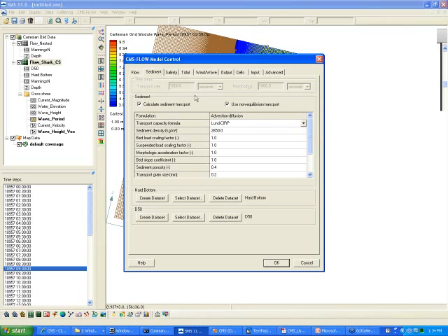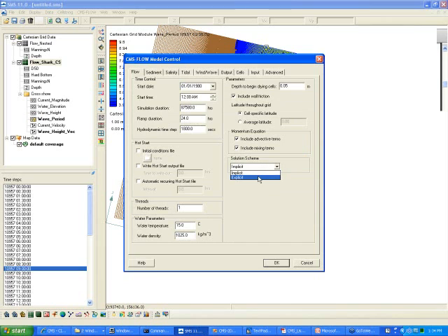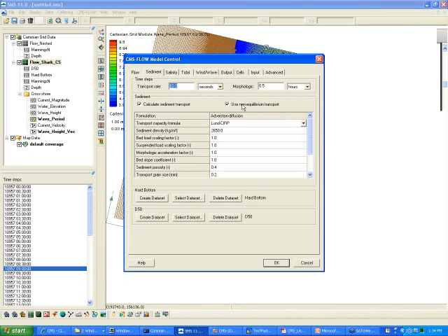If you select the explicit scheme, then you can select the total load non-equilibrium model here, or you can choose advection diffusion. What that means is the equilibrium bed load plus AD equation for suspended load. And then total load refers to the Exner equation. Those two options are only available with the explicit solution scheme at the moment.